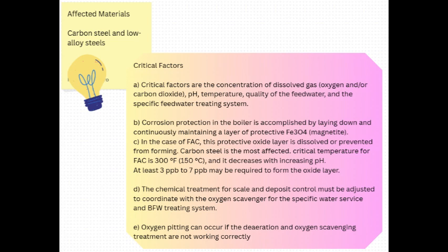And that leads to something I saw mentioned, threaded connections. Why are they called out as being particularly vulnerable? That's a great point. It's about geometry. Those threads, or any fitting really, like an elbow or a flange, they create turbulence. Right, interrupts the smooth flow. Exactly. And that turbulence can help concentrate the corrosive stuff, let it hang around and attack unevenly. But that idea, flow and geometry, takes us straight into the second big problem, flow accelerated corrosion, FAC.